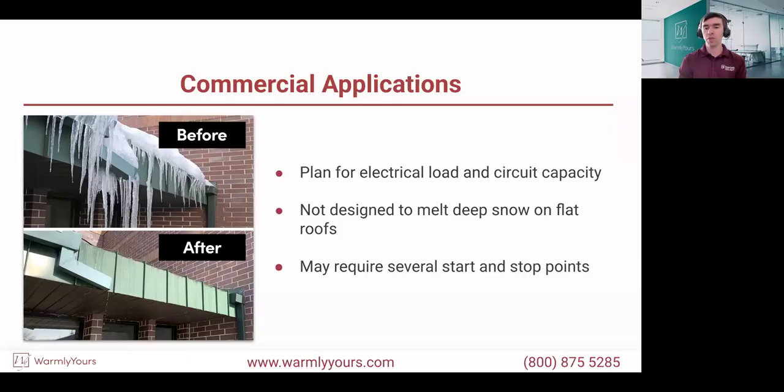Good point. I feel like we didn't touch on this particular benefit of the product too much. Self-regulating cable is, like Mary said, sold by spool, but it's a cut-to-length product, meaning that you can cut it to the length you need. We will estimate and do all the planning for you, but things happen, right? Maybe there was some drain or downspout missed. You're operating with a spool of cable that you keep installing until you either hit the end or hit some termination part of the project where you just cut the cable and terminate it. So I think what we're trying to say is it gives you so much flexibility.